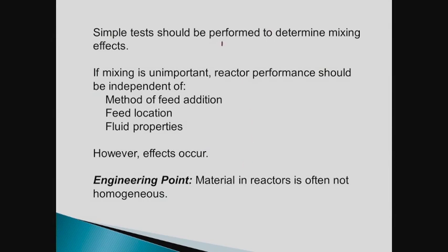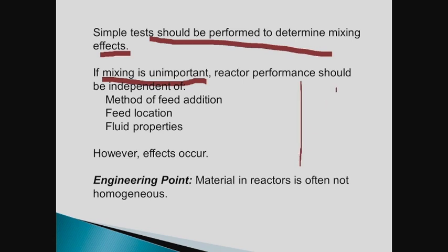Simple test to determine if mixing effects are important. Look at it this way. You have reaction time, and then you have mixing time. Now, if the reaction time is very, very long, it doesn't matter about mixing. Mixing is over with a long time ago. Mixing, remember, is easy. If you have a very slow reaction, then the mixing will have very little effect.